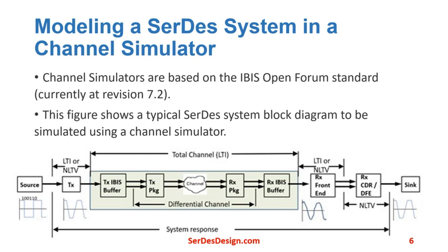The constituent parts of this SerDes system include the following: the transmit IBIS-AMI portions, where the AMI portion typically contains a transmit equalizer, often in the form of a feed-forward equalizer. The IBIS portion provides a differential output to the channel. There's the transmit package, the channel, and the receive package. These pieces represent the differential channel. Each part is optional and may be represented using S parameter files.